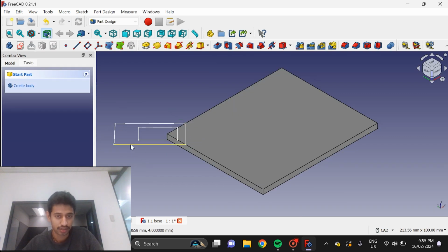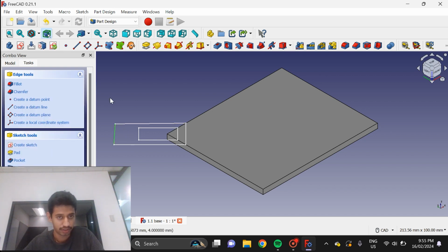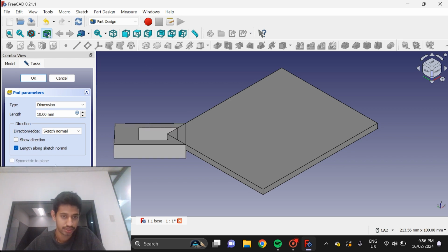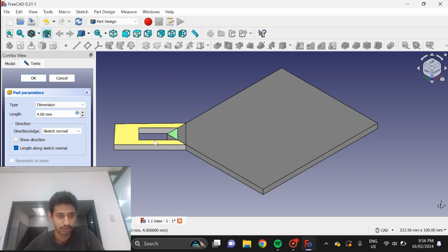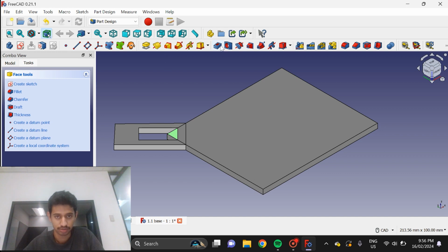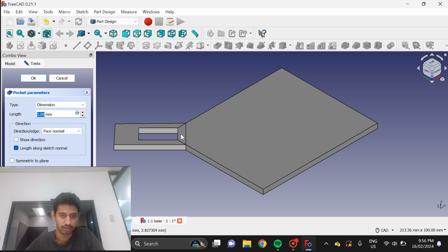I will now select the sketch, and once I've selected it, I'll go pad, I'll say reversed, and pull this down so that it's at the same length. Right now it's 5, it needs to be 4 millimeters. That is good. First you accept this change, and then here you select extrude, and this creates a pocket and gets rid of this.